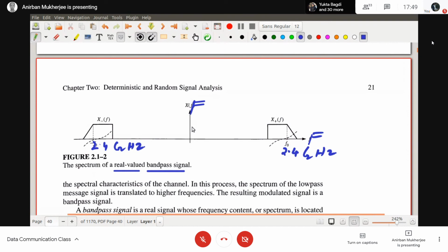Now, if you say you will not project your signal into complex space, there are some transforms, with capital X of some other variable, where you take the integral of x(t) times cos omega t instead of e to the power minus j omega t. So you are projecting onto a real valued function. Are you getting my point, or shall I go much deeper?